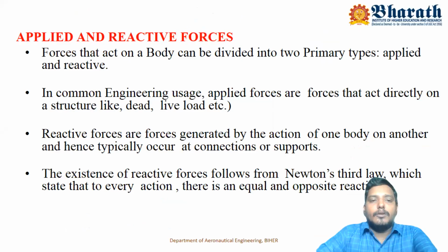Before entering this topic, I would like to recall some fundamentals of structural mechanics. The forces that act on a body can be divided into two primary types: one is applied force, another is reactive force. An applied force is a force directly applied on the structure, maybe a dead load or a live load. A dead load does not vary with respect to time. A live load varies with respect to time.